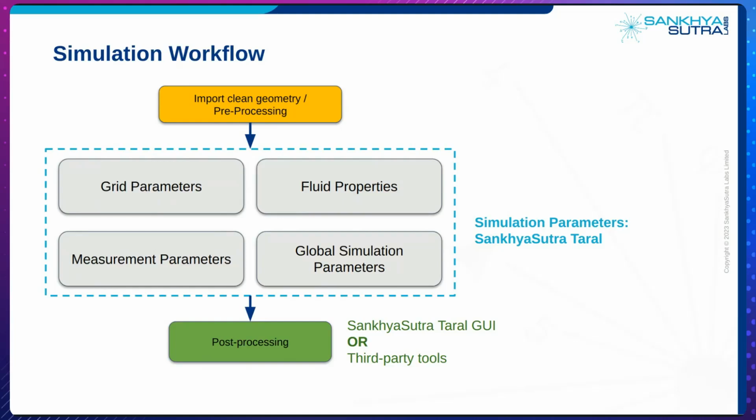And what we call measurements are essentially dumps of data at user specified frequencies that the user might post process to achieve their quantities of interest. And last but not the least, we have the global simulation parameters, which is the total amount of time in the simulation frame that the user wants the simulation to run for, and other parameters such as the global project resolution, etc., which I'll talk about in more detail while I'm doing the hands-on demonstration for you.